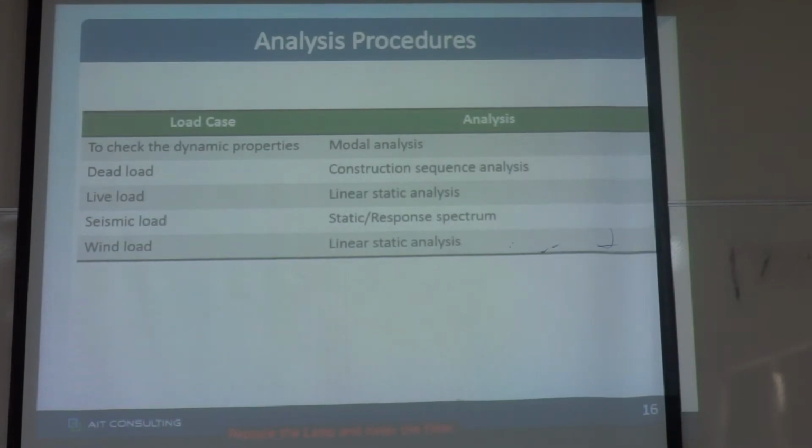But in reality, it will not be that much. It will have some, but not too much, because you analyzed at only one time. So due to that response, the beam connecting the wall and the column will have large shear due to that differential shortening. To avoid those things, we should conduct the construction sequence analysis.